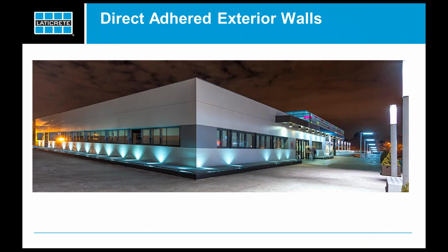Some of these finishes can also be used for exterior veneers. But just keep in mind that if you're going to use them there, consult with your local building code as to tile panel size, facial dimensions, and also thickness. Those can both come into play on exterior veneers.